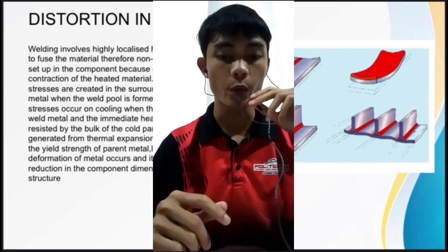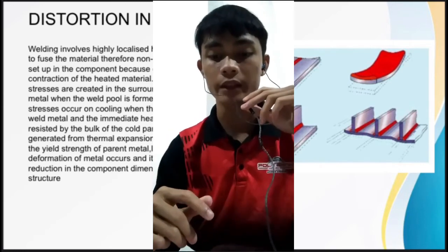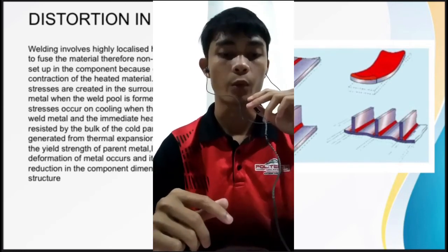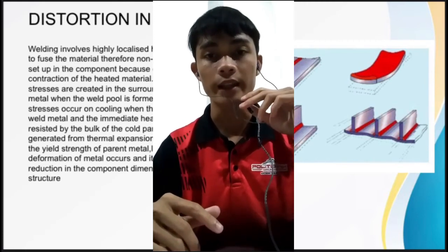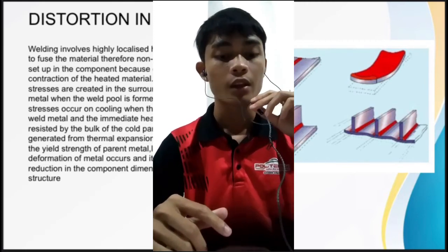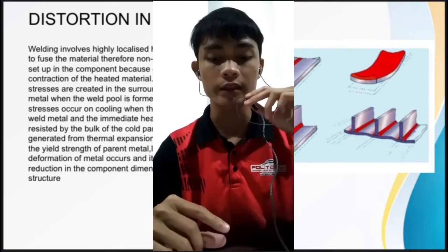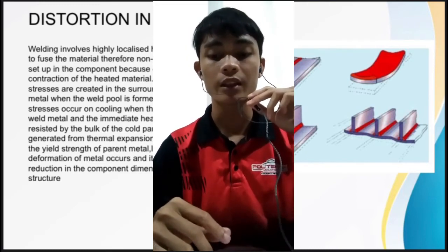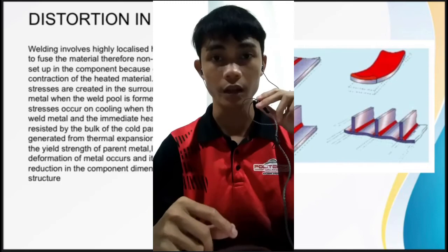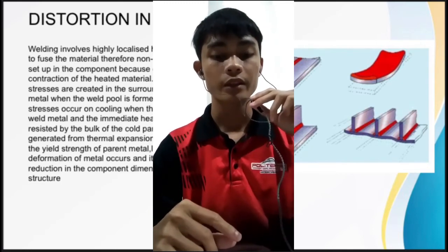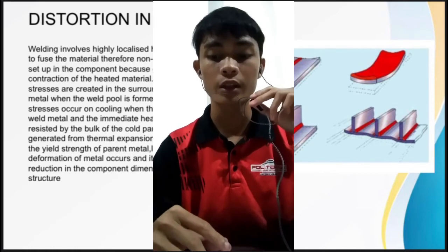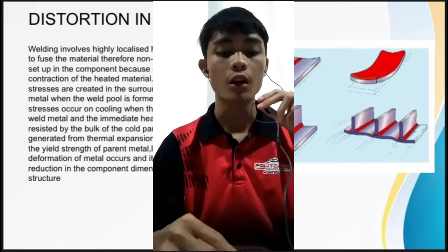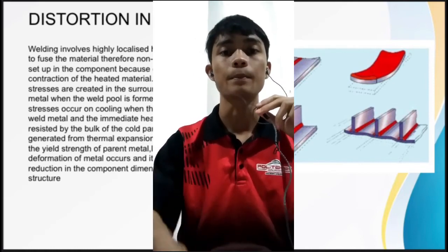Longitudinal bowing in welded plates happens when the weld center is not coincident with the neutral axis of the section. Twisting in the box section is caused by shear deformation at the corner joints. This is caused by unequal longitudinal thermal expansion of the abutting edge.